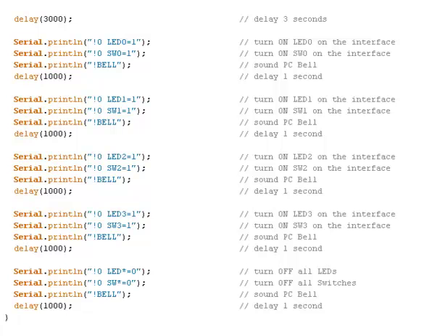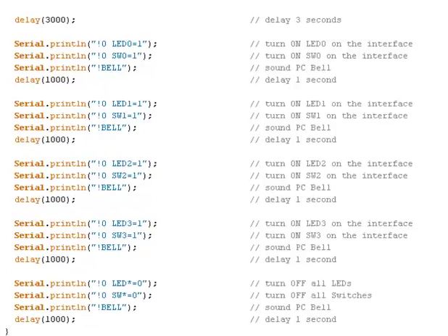Right after putting up the control from Arduino message, we're going to delay 3 seconds. That'll give us time to swing over and look at the LEDs and toggle switches that we just talked about. And what we're going to do there is turn on the LEDs and toggle switches one at a time. And we'll do that by issuing the following commands to MakerPlot.